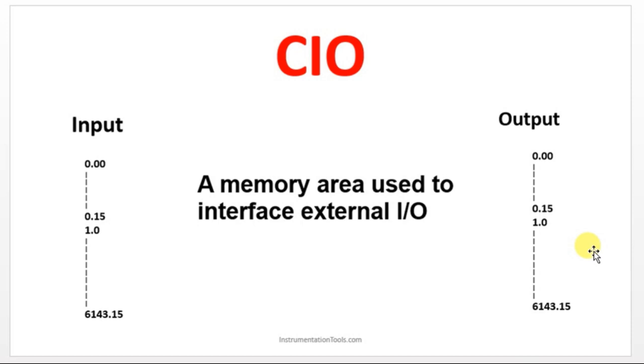And if you want to use some memory coil, you can make use of 10.0. So memory coil in Omron is addressed as 10.0, 10.1 like that. The expansion module output address will start from 102.0, 102.1, 103, 104 like that for the expansion output module. So for input 0.00, for output 100.0, and for memories it will start from 10.0.